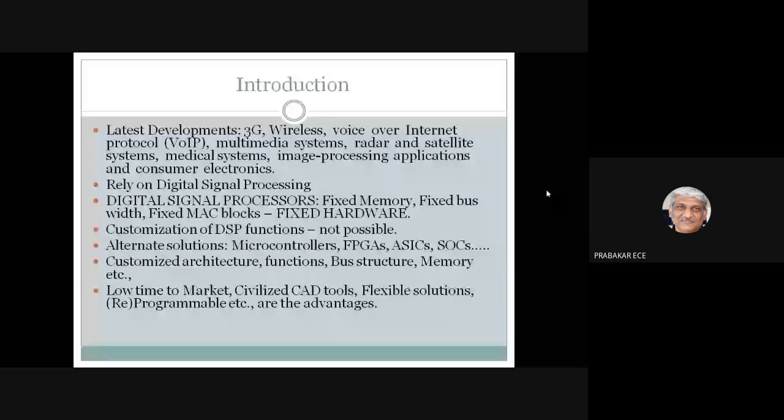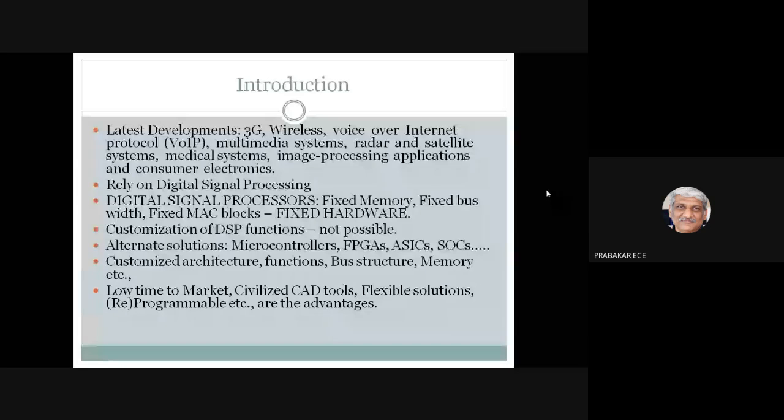So the hardware is also configurable. The other advantage is the number of pins available, because most of these devices have multiple data streams coming in; it is already big data, and the number of devices is also very high. Here I can have many pins available, so that I can take the data in bulk and process it. Compared to microcontrollers or DSP processors, FPGAs have more pins. And data processing will be concurrent, which is another advantage.